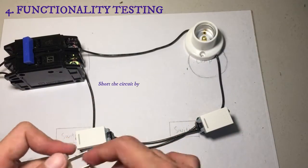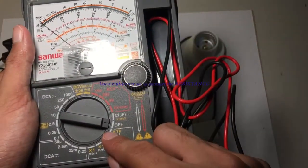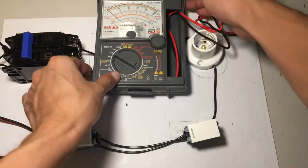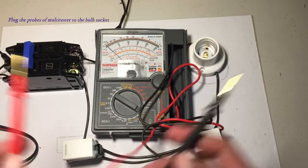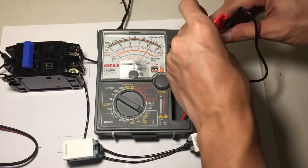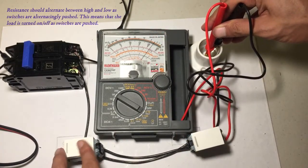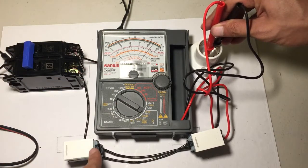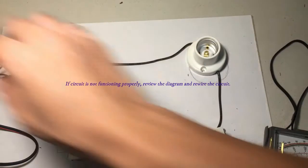To test for the functionality of the circuit, insert a wire between the plug. We will use a multi-tester in order to test for the resistance. Turn the circuit breaker on. Plug the probes of the multi-tester to the bulb socket. Then alternatingly click the switches and check if the resistance alternates between high and low. If it does, then it is functioning properly. If not, review the diagram and rewire the circuit.